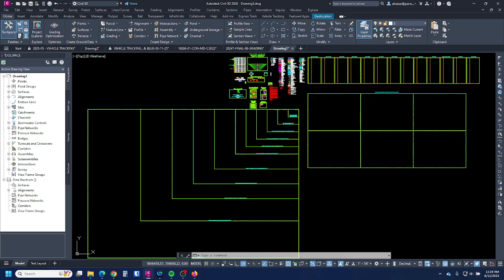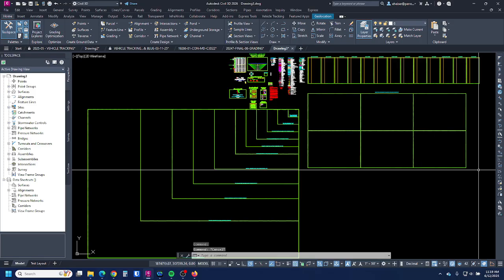So Civil 3D now has the ability to create those objects and actually import rainfall data and basically pass flows through those basins. You can connect it to your storm sewer pipe networks and route the pipe network through the basin. And it'll give you hydrographs. It'll give you your hydraulic grade line on your storm profiles that you draw. You can upsize your pipes and have it recalculate and see how it changes things. It does a lot of similar things that HydroFlow does, but you definitely need to do more upfront within CAD to make it work.